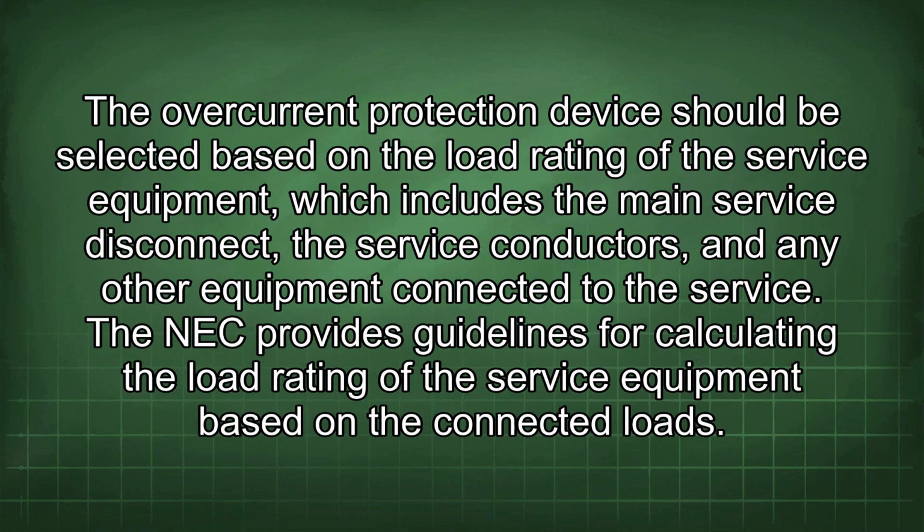The overcurrent protection device should be selected based on the load rating of the service equipment, which includes the main service disconnect, the service conductors, and any other equipment connected to the service. The NEC provides guidelines for calculating the load rating of the service equipment based on the connected loads.